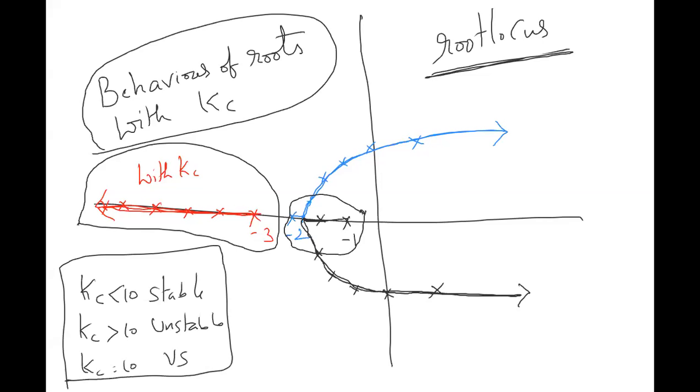Somebody of you might be operating in the plants, but when you open the plant operations, you don't see Kc, 1 by tau i, 1 by tau d. You just see the parameters. What is my band? You will fix, let's say, 100% to 0%. But remember, band is inversely proportional to Kc. I have one problem with respect to band, I will tell that problem also. But in the plant terminology, this Kc will translate to band.